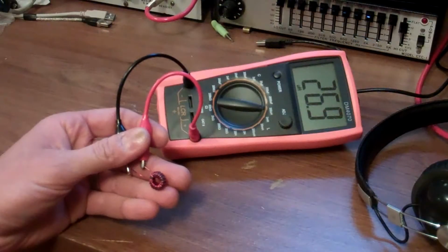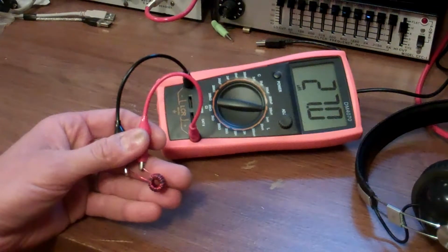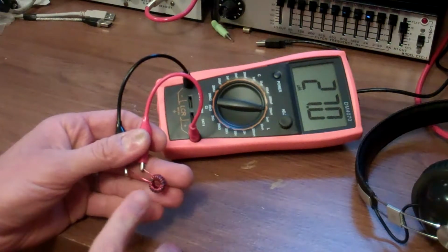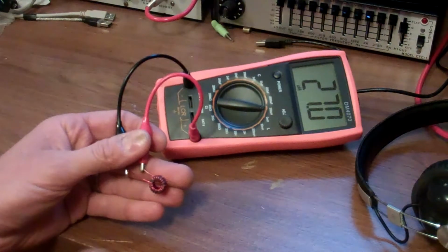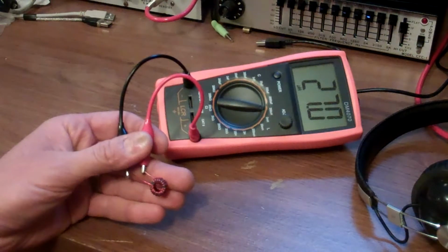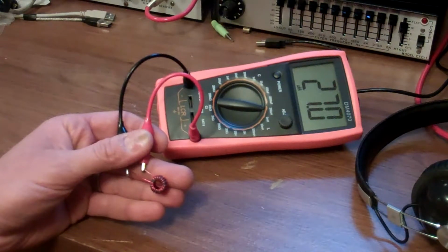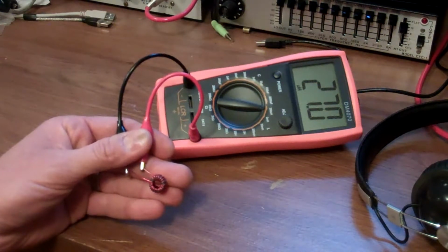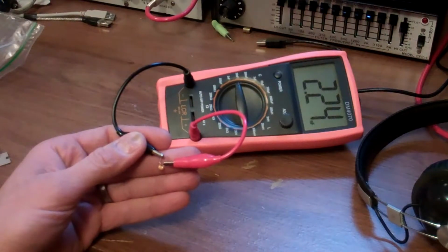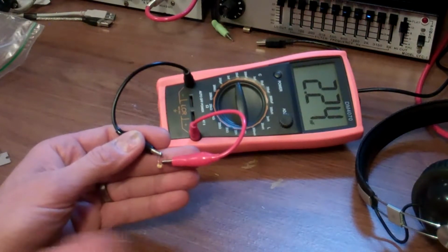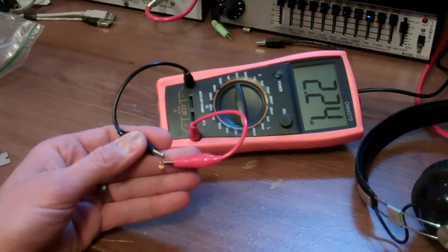You want to scrape off enough so that when you solder, you don't have soldering issues. After I'm done constructing my toroids, I'll put them on my LCR meter to get the exact values that they are, and I can adjust them turn by turn, either taking turns off or adding turns to get them closer to the values in the schematic. But after they're designed and they're as close as I can possibly get, I'll measure them, write down their values, and then I'll go back and readjust the schematic for the exact values that I've measured in the actual final build of the transformer.